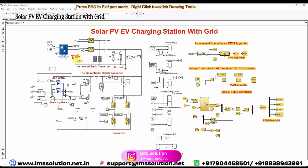This voltage should be stepped down to 400 volts, because we are going to maintain the DC bus voltage at 400 volts, so 500 volts is going to be stepped down to 400 volts. For that, here we are using an interleaved buck converter. This is the structure of the interleaved buck converter.